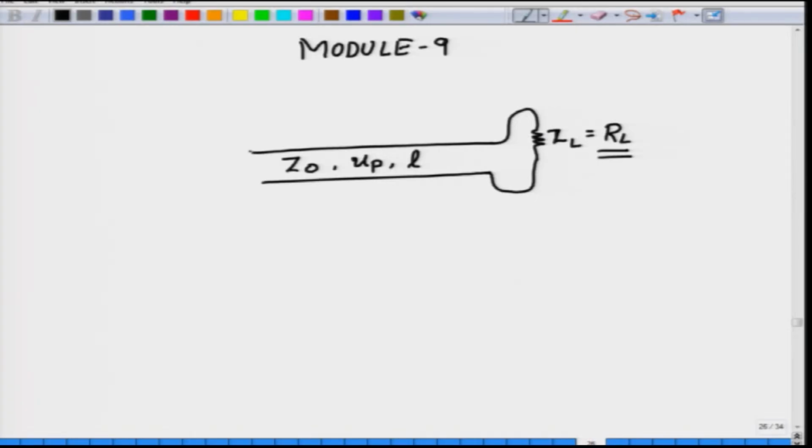The excitation that we are going to give to the transmission line will again have some load, which could be just a resistive load. In this case I will call this ZS. Please note that I am not calling this Zg. You could of course call it Zg as well, it does not really matter. I am calling this Zs to indicate that these are source quantities, because this terminology is quite common in signal integrity applications, or in time domain behavior applications. You normally do not write it as Zg, because Zg is usually reserved in the RF circuit literature.